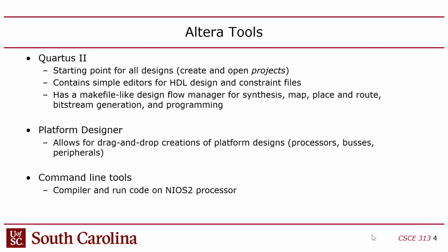That's the same kind of architecture you have on your phone's processor. But now, because you're building this on an FPGA, you can customize it for the application that you want, right? Whereas the one on your phone is an ASIC and it's fixed, right? So that's Platform Designer. And then in previous years, we used Eclipse to write the software for the processor that we put on the FPGA, and now we're using command line tools because they're a little bit more reliable.